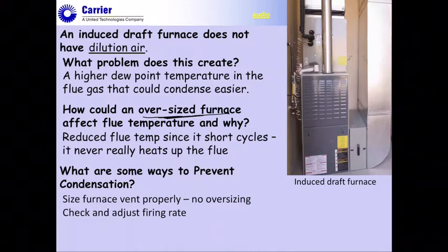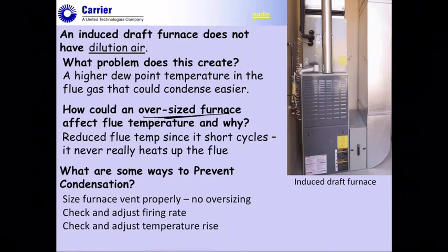How do you do that? Make sure that you're getting your BTU input appropriate to that furnace. For a two-stage furnace, it's important, but if you're running it on low fire, it would be an even bigger issue. So that's a little bit of a problem. Also, check and adjust your temperature rise. This is where your fan speed comes into play.